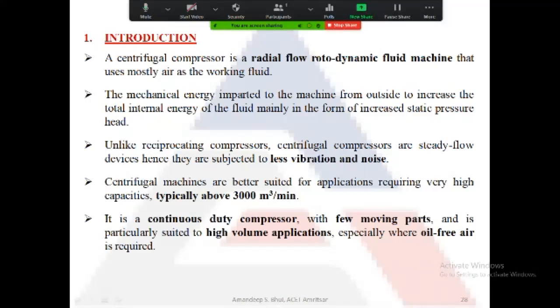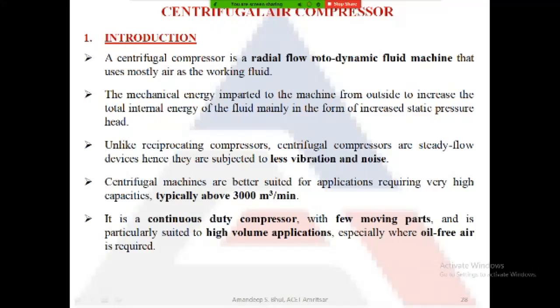Rotodynamic means it is a rotating device, so hence the word roto is there. Dynamic means we are changing the dynamics of the air. So hence it is rotodynamic, where the rotation of the impeller inside the centrifugal compressor increases the kinetic energy of air. Because of the rotation, the dynamics of air are changing.